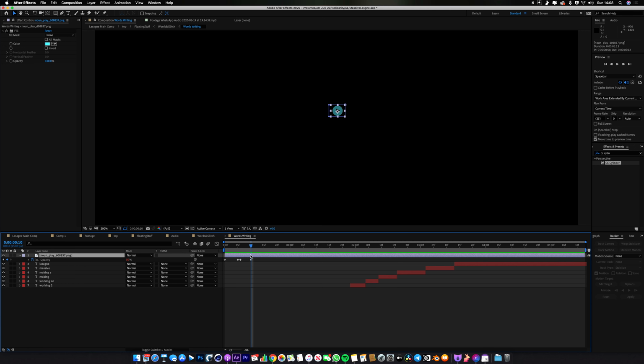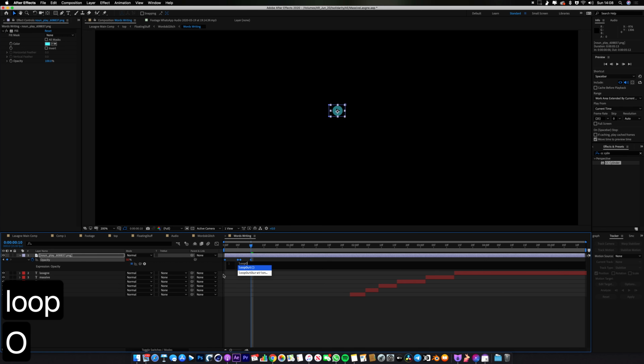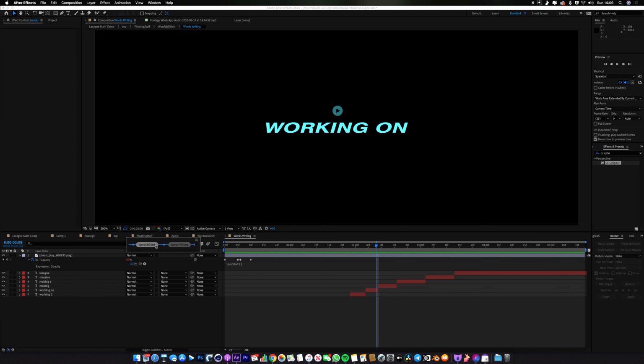And then to 50. And then I've done a little expression here where what you do is you alt click on the stopwatch. And then we're going to go loopOut like that with a capital O. And that's just going to make the thing loop the whole way through. So it's just going to go 150, 150 to give us a bit of a pulse. So let's just go back into the comp above that.